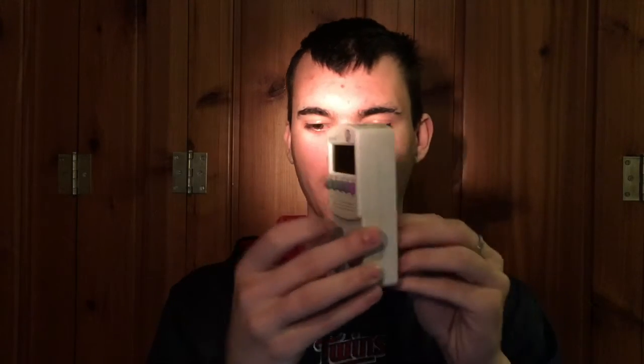This device here is called a kilowatt meter, and it's what I use to measure power coming from home appliances. It simply plugs into the wall at this end, and the appliance comes in the front here. There are several modes to measure the power, namely watt mode and kilowatt hour mode. For appliances with constant energy consumption, use the watt mode. For devices with active power and phantom draw, or variable energy units, use the kilowatt hour mode to measure power consumption over a day's use.